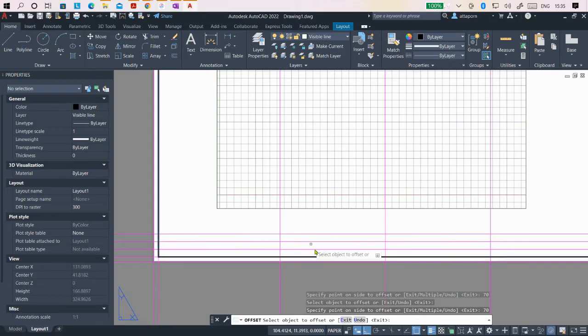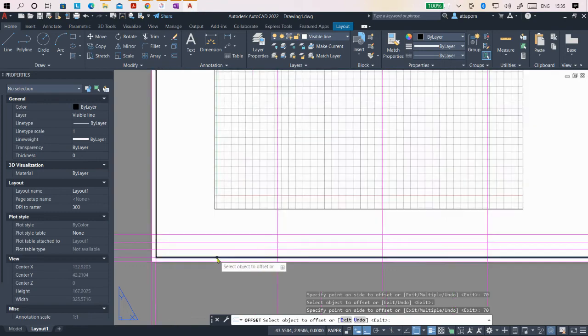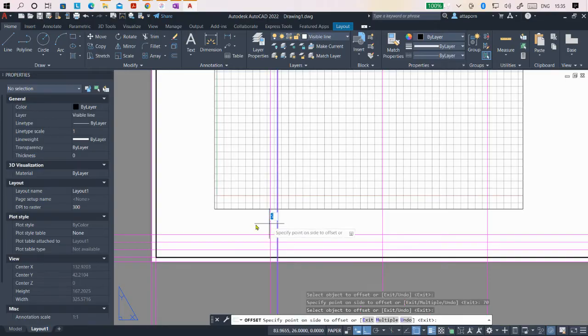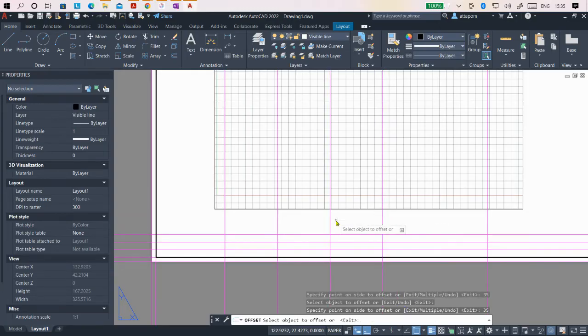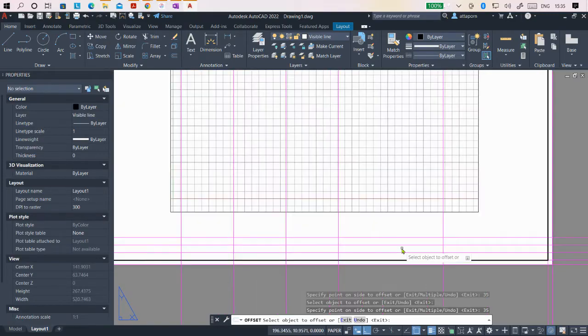The last column is maybe more than 70, it's okay because it's for the title, which is quite long information, okay, so it's wider like this. Okay, so maybe we have some sub columns here, maybe this for 35, okay, and 35. If we have sub columns here, so here is the project, and this one like the material, page number, sheet of, something like that.